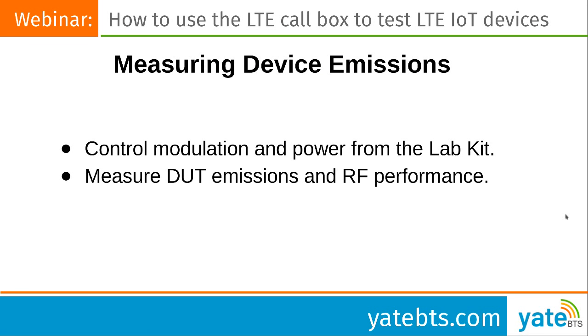Okay. The next thing that you can do with a lab kit is you can do hardware testing and measuring device emissions. So if you have a device that's going to be installed in a situation where emission control is very important, say on an aircraft, then you will need to do compliance testing to be sure that the emissions that come from your device aren't going to cause what they call electromagnetic compatibility problems in the place where it's going to be installed.